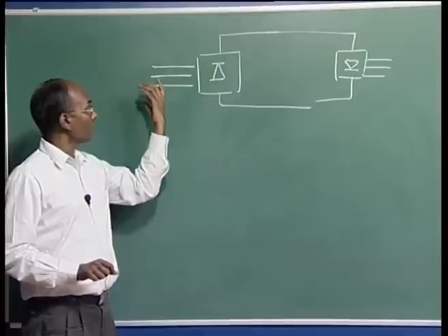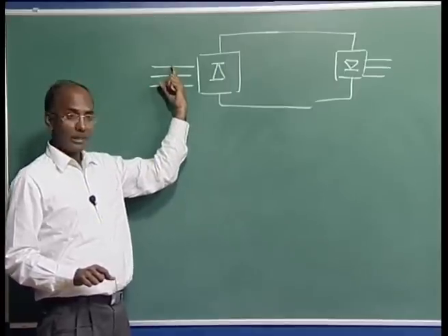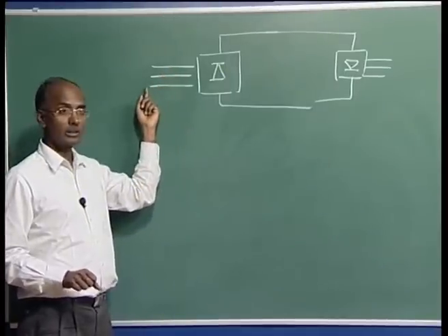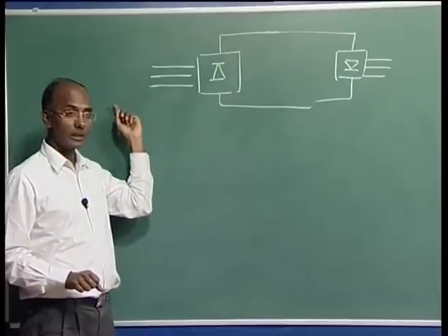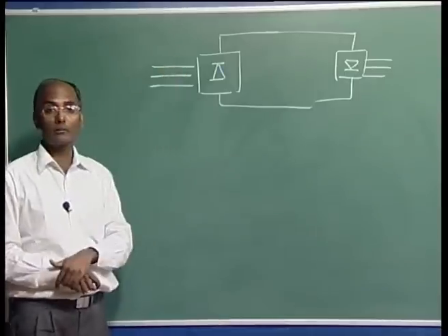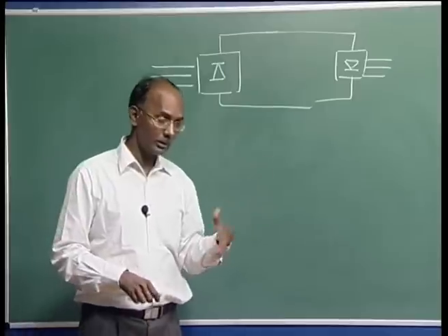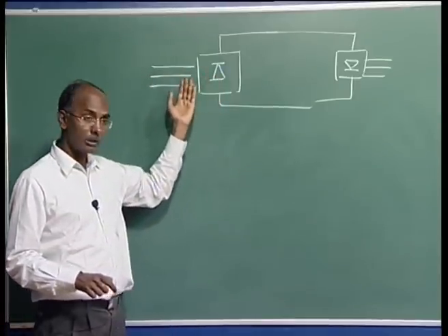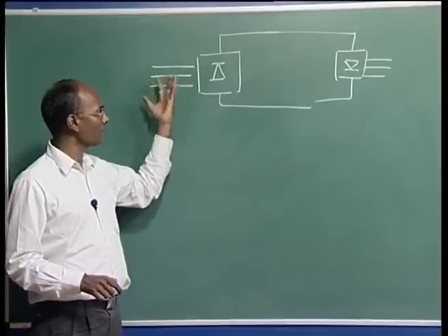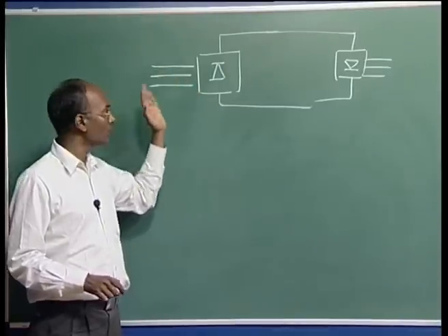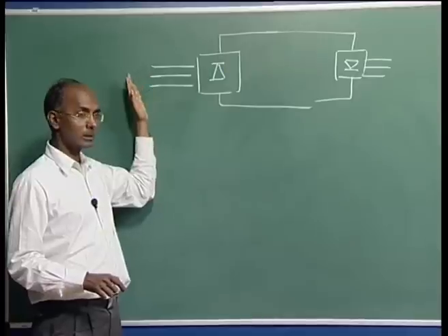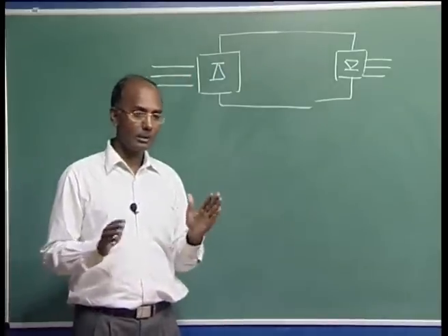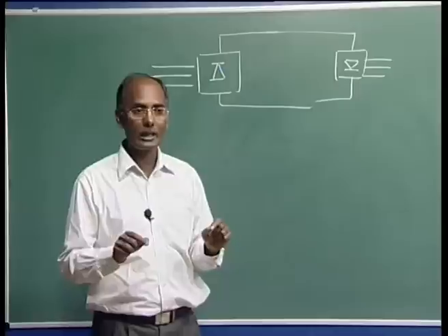The voltage may also rise depending on the asymmetrical fault. If there is a fault in one line and the neutral is not connected properly, the voltage of the other phases may go above normal. The converter may experience overvoltage, or undervoltage and sag, and of course sometimes the voltage may be 0. I am not going to discuss this in detail, because we are not concerned with the AC protection system. Our concern here is HVDC faults and protection.